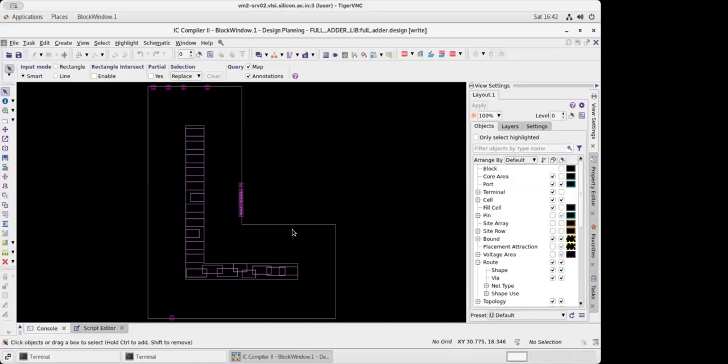See, it's not there. That means when you ran the DC, the last command which I asked you to run, you haven't done that particular part. Just do one thing. CD space dot. Enter. LS. So result reports, yes, that was missing in your case. Okay, so you have to run DC once again. And you have to write that particular command which is already part of DC dot tcl. Just open this, run DC dot tcl. Open this, I will tell you which command.